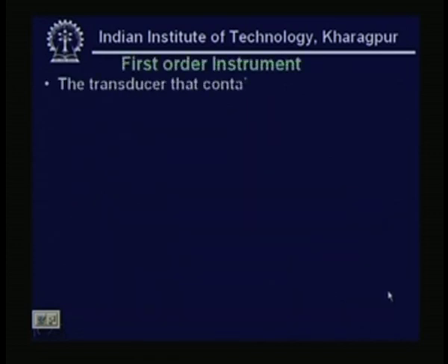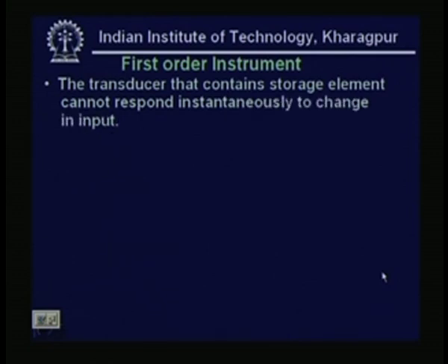You can see here that the potentiometer always shows whatever input it gets immediately at the output, without any time lag or phase change. That actually happens in the case of a potentiometer. That means whatever inputs you are giving, it immediately appears at the output. I can use it as a position sensor also, because the output voltage is directly proportional to the position. What is that position?